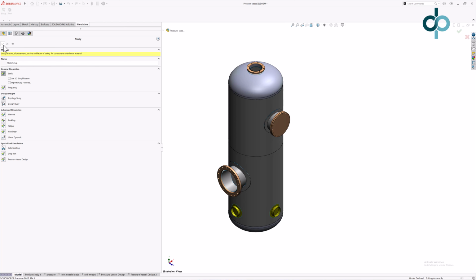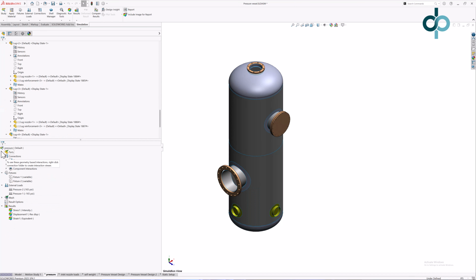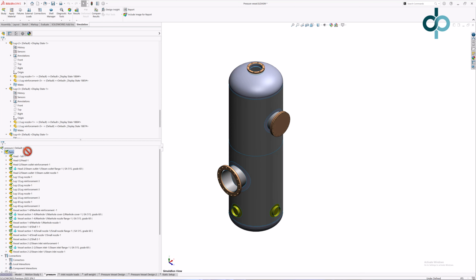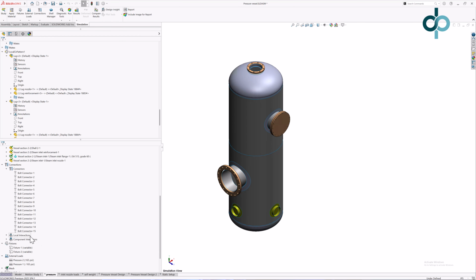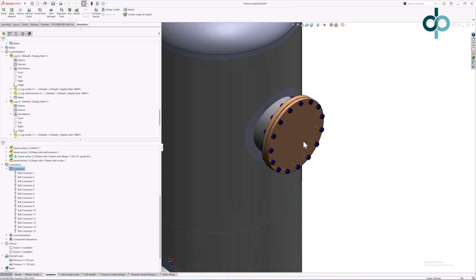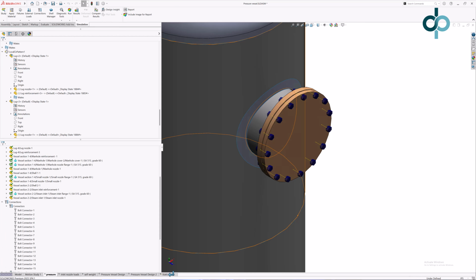First is the material and geometry setup. It's steel, and the thin pieces were shells, and the thicker flanges were solid elements. I can drag the setup pieces from one study to copy to another. Next is the connections, or how the geometry interacts with each other. In this study, we used virtual bolt connections to accurately account for their effect without adding to the simulation time. These are great time savers that don't cost anything in terms of accuracy.